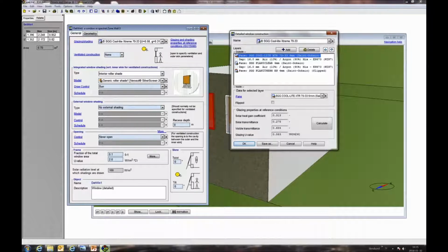Earlier, and that's a common way to do this, we used to calculate the combined properties of all these different spectra, and then calculate the properties of the whole pane by pane combination. The problem with that is that you cannot capture the nice features of modern glazing and shading material. So now we do this totally spectrally.